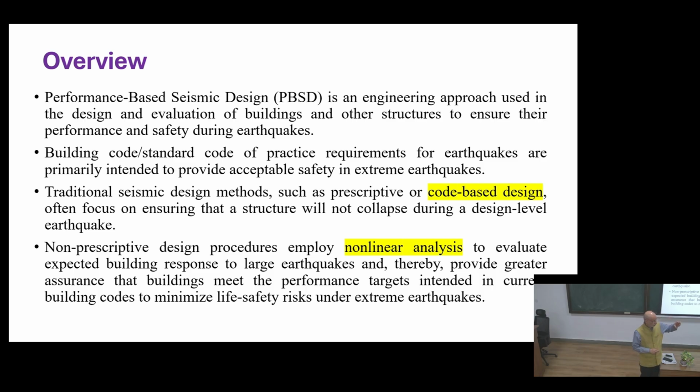So you expect such a large force due to the earthquake, because the earthquake itself is not a force, it generates a force. Earthquake is basically ground oscillations, which are transferred from the ground to the structure. When the oscillation comes into the structure, it may amplify the ground motion, depending upon the characteristics of the structure, or this energy is dissipated through certain mechanisms within the building as you design it.